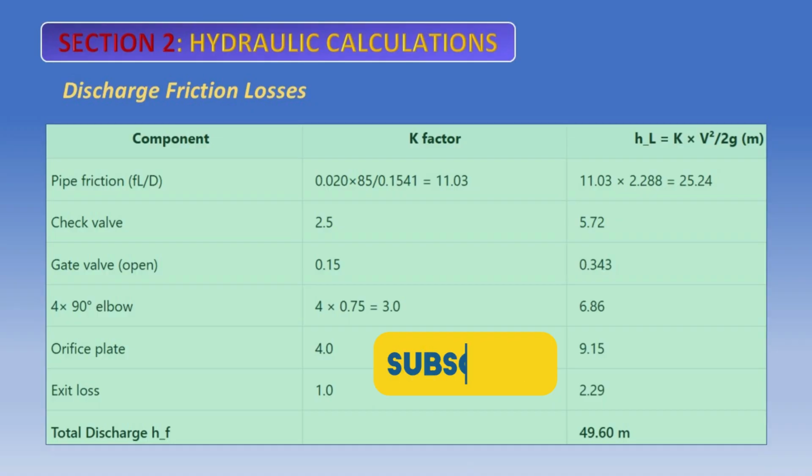The losses from fittings are also substantial, with 4 elbows and an orifice plate. The orifice plate, which is used for flow measurement, creates a significant pressure drop of 9.15 meters. The total discharge friction loss is a massive 49.60 meters. This is the dominant component of the system's friction losses.